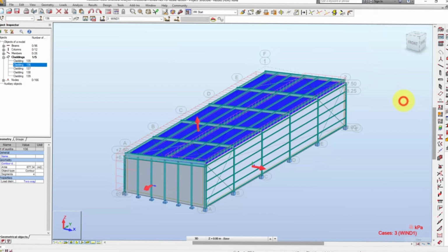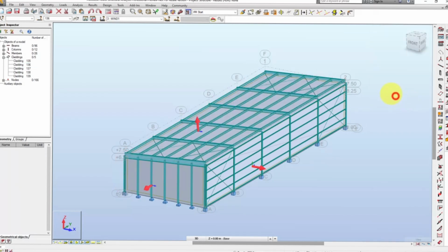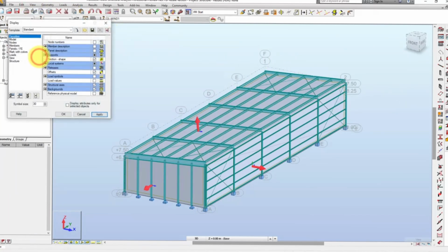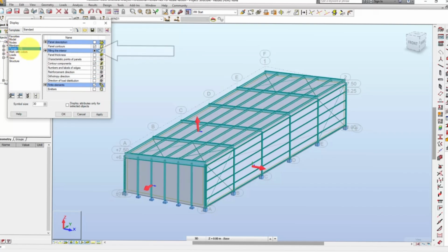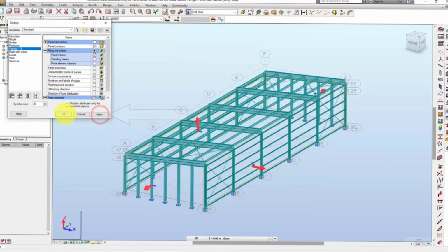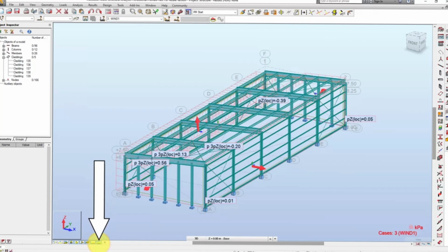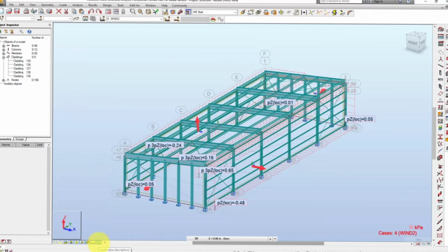Click Close. To inspect the load case, from the text menu, select View Display. From the Display dialog, from the menu, select Panels. Expand Filling the Interior, and then deselect Cladding Interior. The interior of the cladding in the drawing space becomes invisible. From the views, enable the load symbol and load value descriptors. The values for the load cases display in the drawing area.